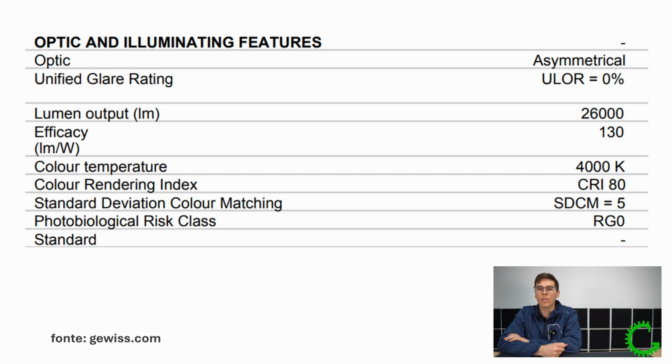The luminous flux is present in the floodlight or lamps datasheet, and it's very important to design the lighting system. If a floodlight doesn't have the datasheet, or the datasheet doesn't have the luminous flux, I will not use it.